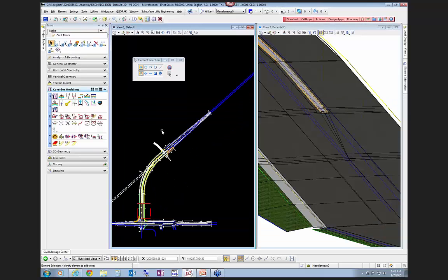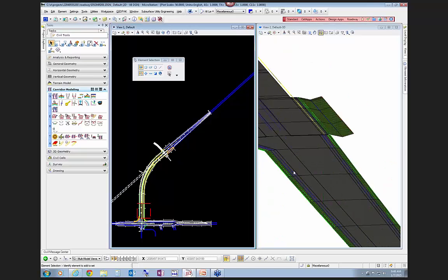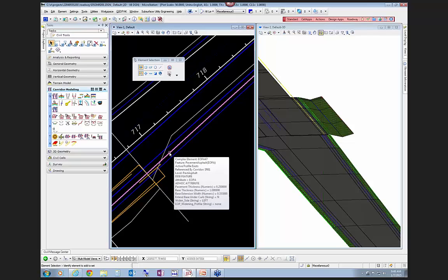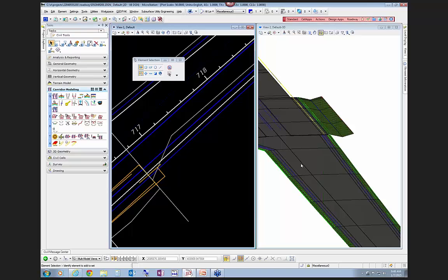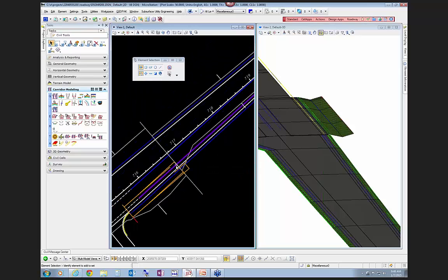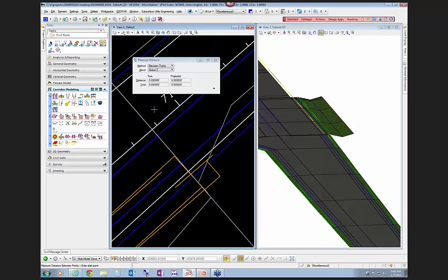So now you see that I've got this, and notice that this side here is definitely not hitting that edge of pavement. And it's either because this isn't a corridor reference, actually it is, or because the reference distance, the range, isn't far enough. Okay, so what I would want to do is try to figure out what is this width here. So I can measure it, and I can essentially just go from here to whatever this width is, and it's probably, all right, somewhere around 36 feet.